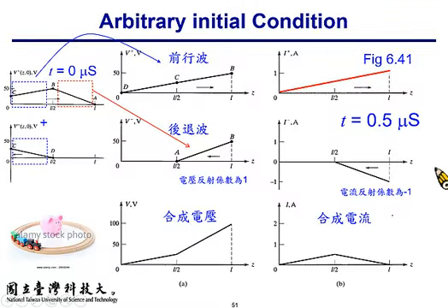As you can see here, the total voltage, as the sum of the two piecewise linear functions, becomes this. The voltage is 0 at the left hand, 25 in the middle, and 100 in the right hand. And as to the total current, it becomes 0.5 and 0. Again, note that the boundary condition of 0 current at the termination, at the end, is still satisfied for the delayed current response. Okay.